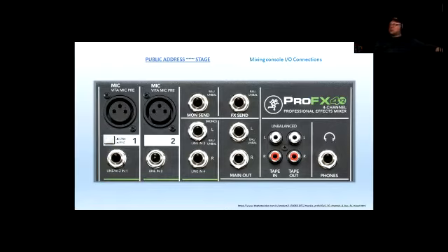Depending on what kind of signal you have, weak or strong: a strong signal would be something from a keyboard, which is an active device that is plugged in, or a CD player, or whatever DJ gear is powered up. That would be the line level signal, about 1 volt peak to peak or so. And the microphone level signal would be about 1 millivolt peak to peak.